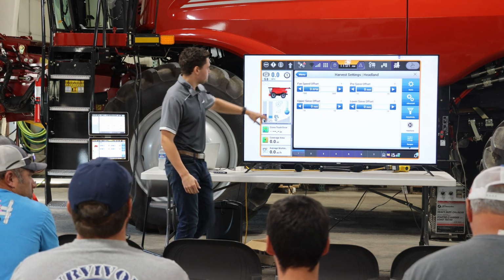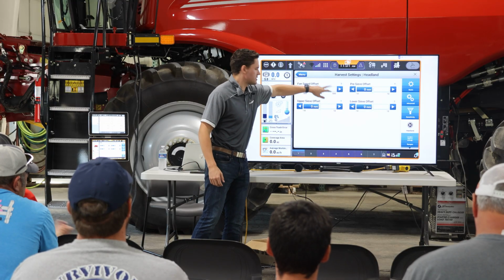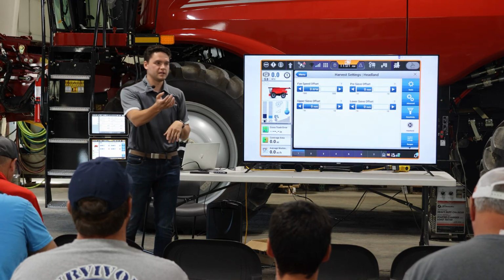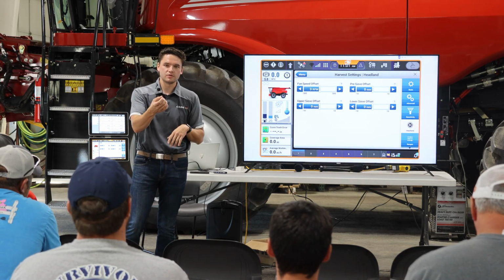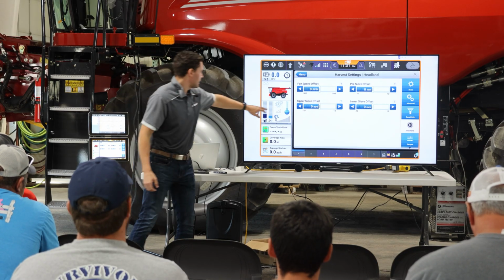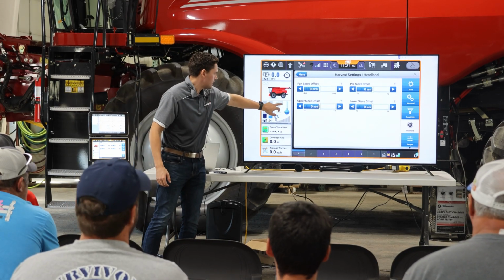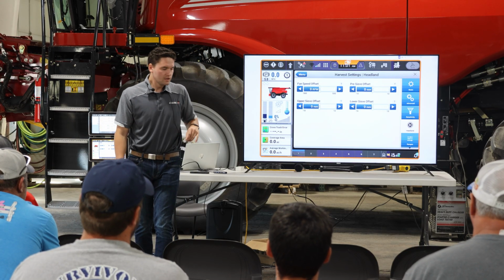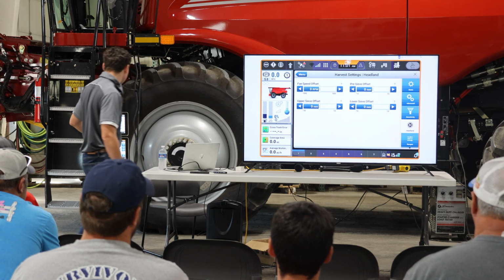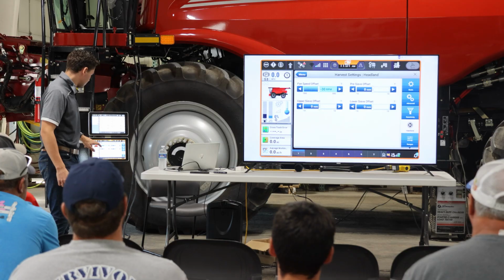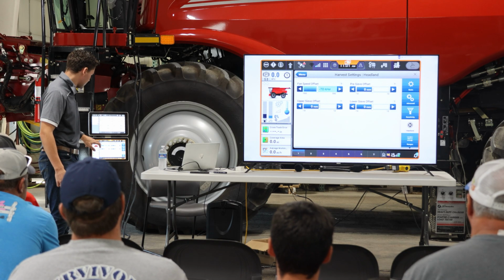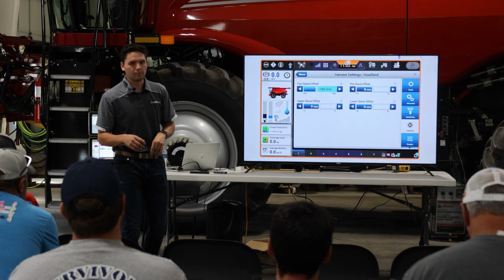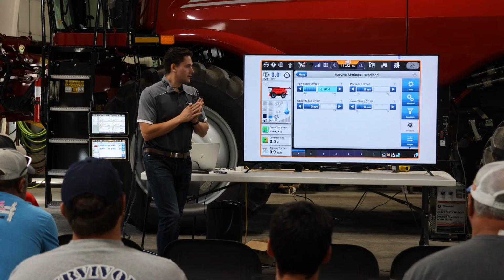So what we can do is we can have automated sequences that happen. Headland mode is a feature of being above max work height or hitting shift and header resume. That takes you into headland mode, and you'll see if it's a 700, this A will turn to an H. On 1200s, it just populates the H right there. What I typically like to see is we'll take this down to a negative 100 or 150. I don't typically mess with the pre-sieve, the upper or the lower sieve.